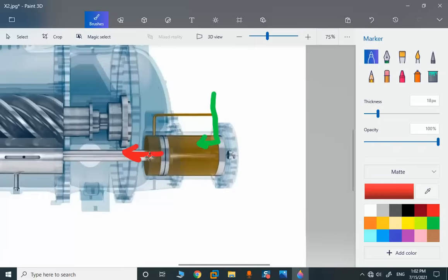So by using two binary actuators that are solenoid valves, it's possible for us to determine the position of this slide valve. With integrating actuators, if there is no command, the slide position will be intact and it will remain constant at that position.